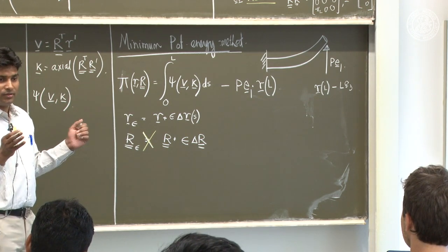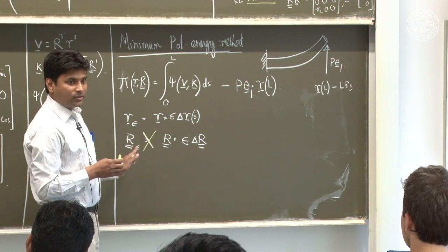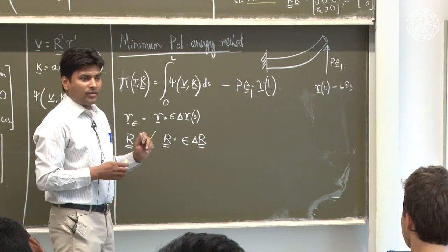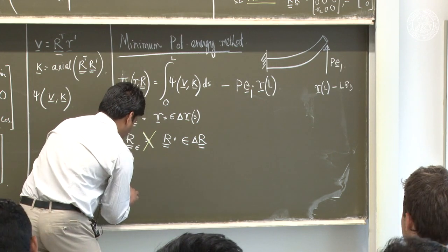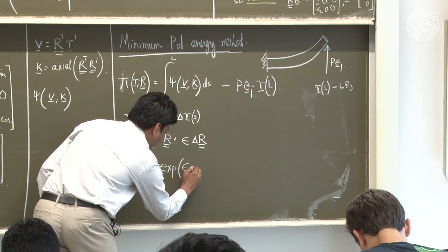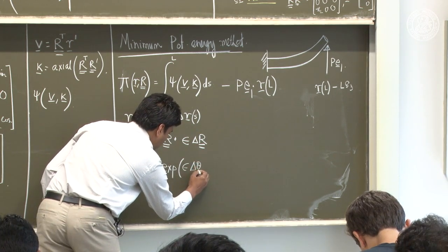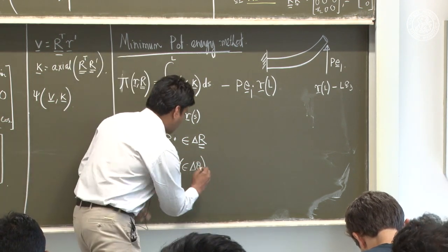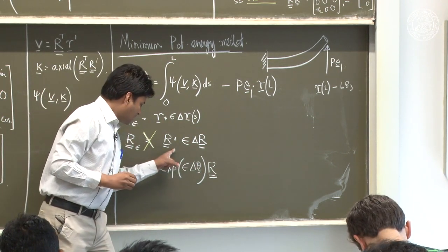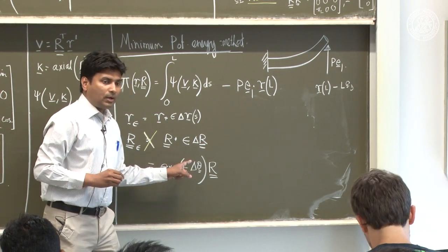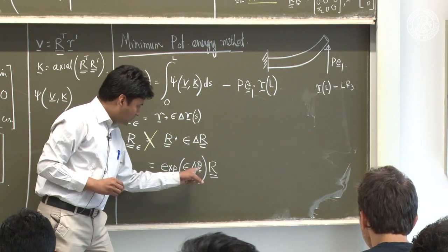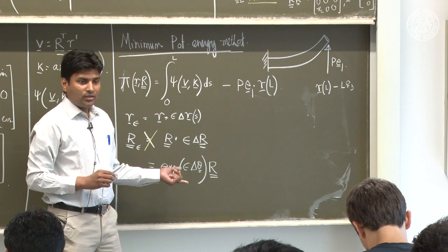That is the most tricky part in this perturbation. Otherwise, everything is as it is in 3D elasticity. So the way to perturb this is you have to think of imposing extra little rotations on top of this big R. And the way to do that would be simply you write that this is equal to some exponential of epsilon delta theta, I will tell you what that means, into your big R. So this is the fluctuation in big R, which is applied on top of the existing rotation, and this delta theta with two tildes below is a second order tensor, and it should be skew symmetric.